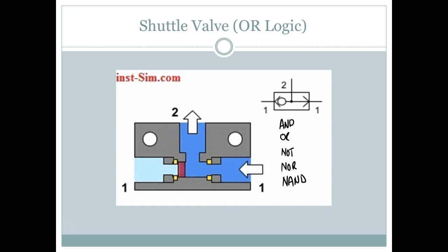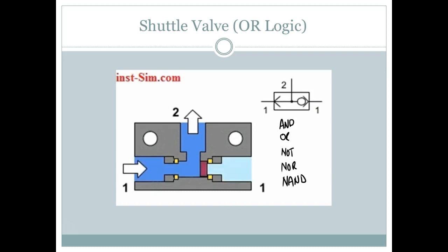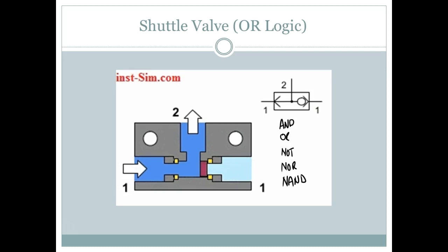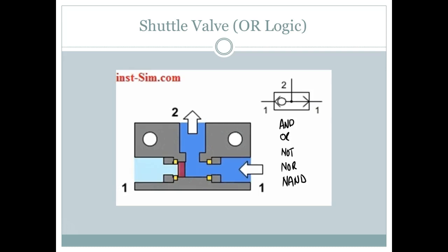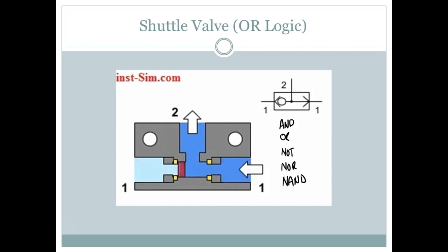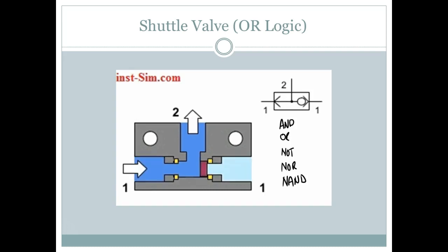I'm looking at it, I'm going like, what would be the purpose of switching sides when you're only going out one port? You know. The example we gave is I've got a big press that puts out 5,000 pounds of pressure, and I've got 2 operators out there. And if I've got that sucker up, I don't want that second operator to have the ability to bring it down.